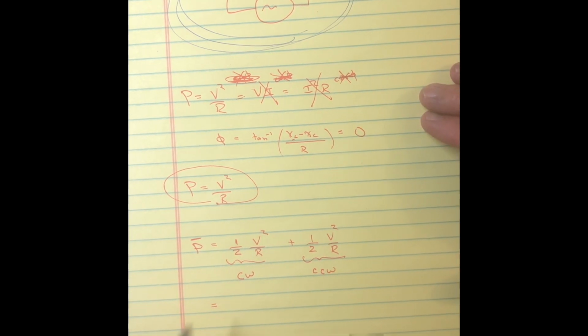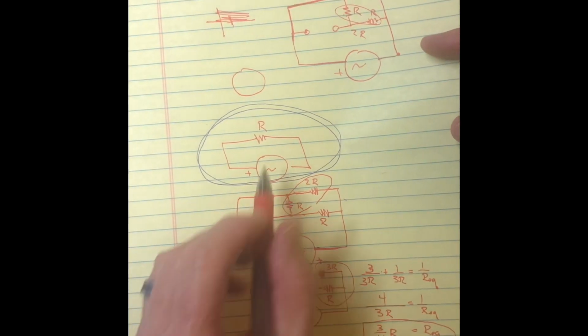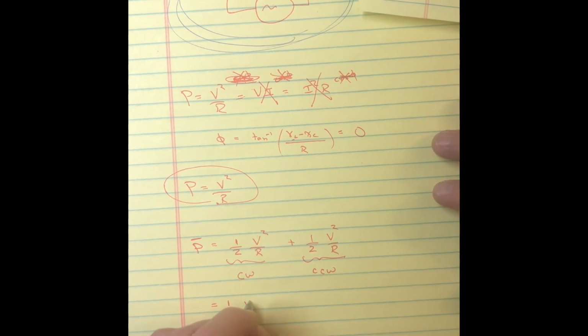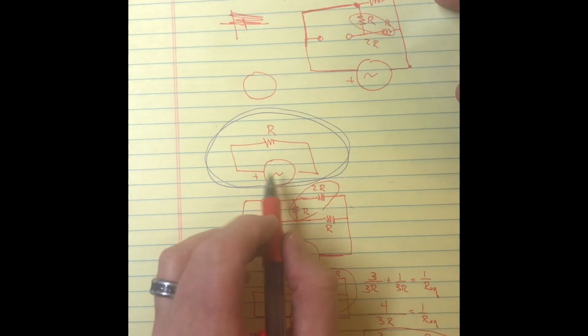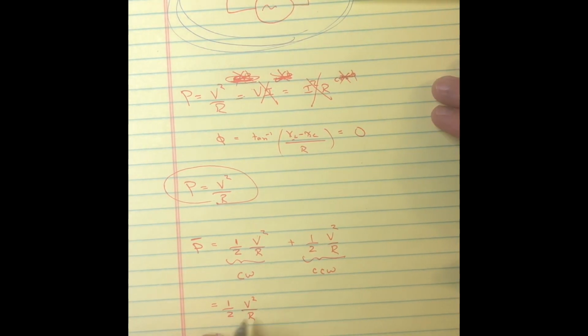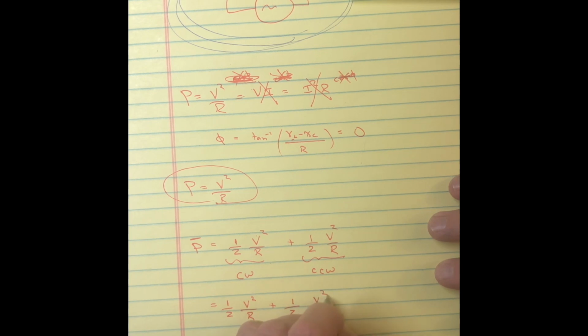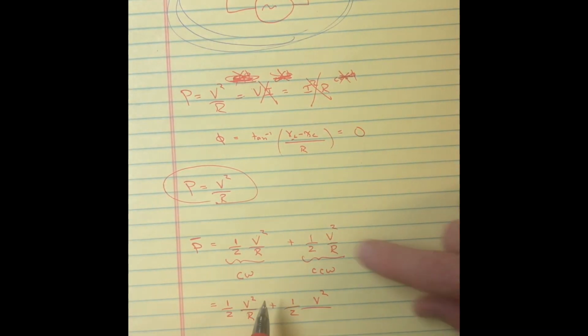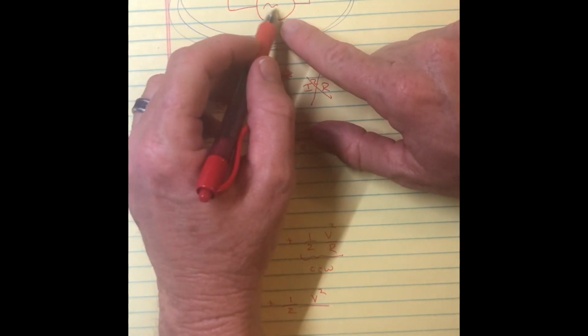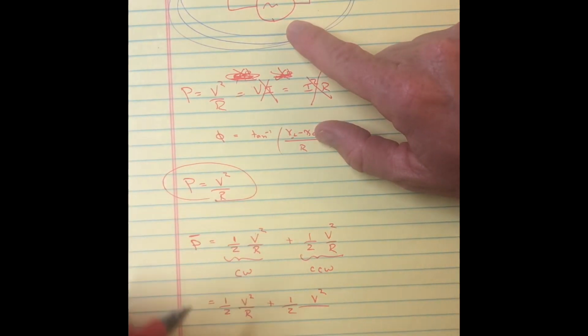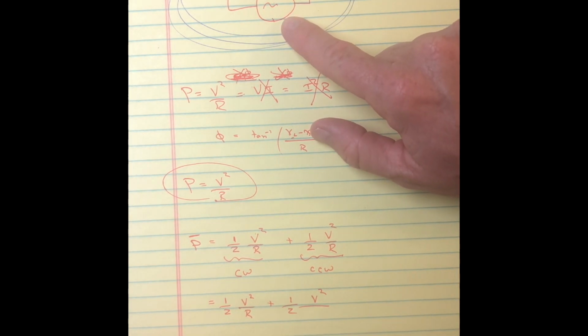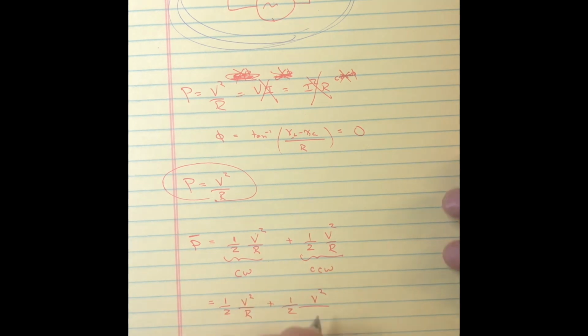All right, and that will kind of finish up the problem. So let me go to the clockwise direction. The clockwise direction, the voltage just is the V, so I can just write that as V squared. And the equivalent resistance is just the R, and so that's kind of a simple translation. The other direction, though, which is what this picture represents, would still have a V because regardless of which way the current is going, the voltage source is still going with the same magnitude here, okay? But then this resistance would be 1.75 R.